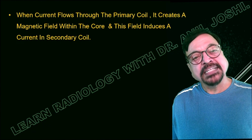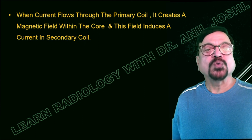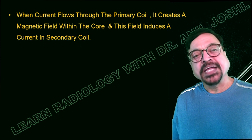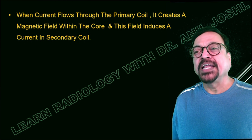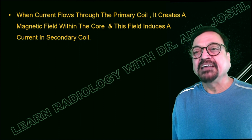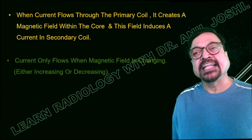As per the requirement, there is a fixed primary which gives around 220 to 240 or 440 volts. From that, we increase the output to the desired potential difference. When current flows through the primary coil, it creates a magnetic field within the core, and this field induces a current in the secondary coil.